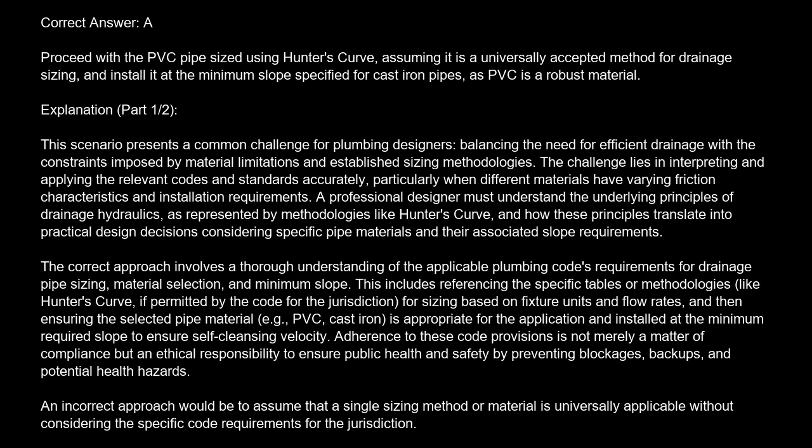The challenge lies in interpreting and applying the relevant codes and standards accurately, particularly when different materials have varying friction characteristics and installation requirements. A professional designer must understand the underlying principles of drainage hydraulics, as represented by methodologies like Hunter's curve, and how these principles translate into practical design decisions, considering specific pipe materials and their associated slope requirements.